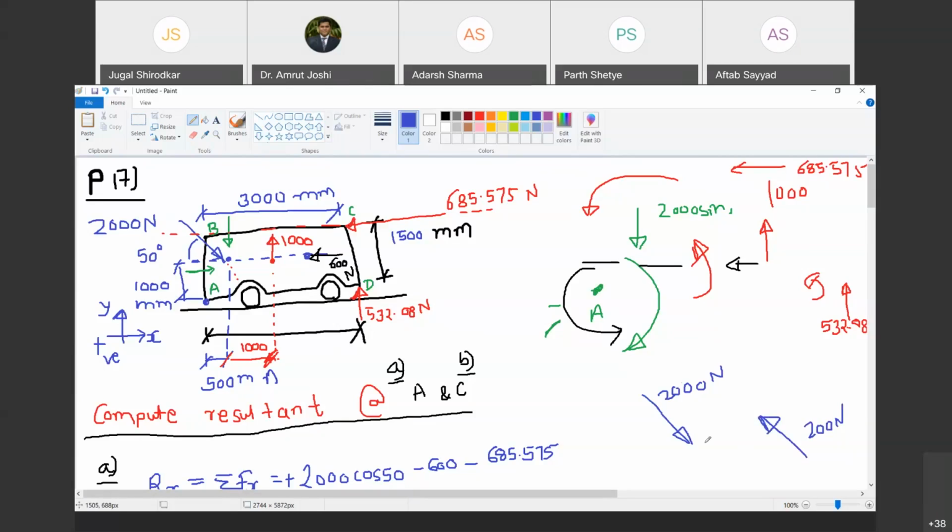Yes sir. Look at the argument. Summation Fx is 0, summation Fy is 0, so Rx is 0, Ry is 0, therefore R is 0. If R is 0, you take the sum of forces in any direction, it has to be 0. Do you agree with me?